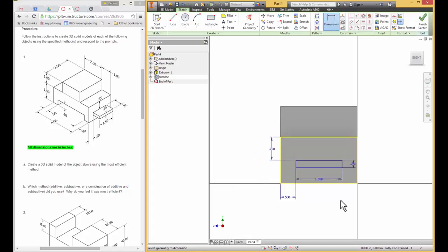And that actually has located, notice it turned from black to blue. We like hornet blue. I'm going to hit escape so that I get off of dimension. Now I can actually pull this dimension down. I want to line up those arrows, and this I'm going to pull off of the part. I want you to get in the habit of not dimensioning on top of your part.